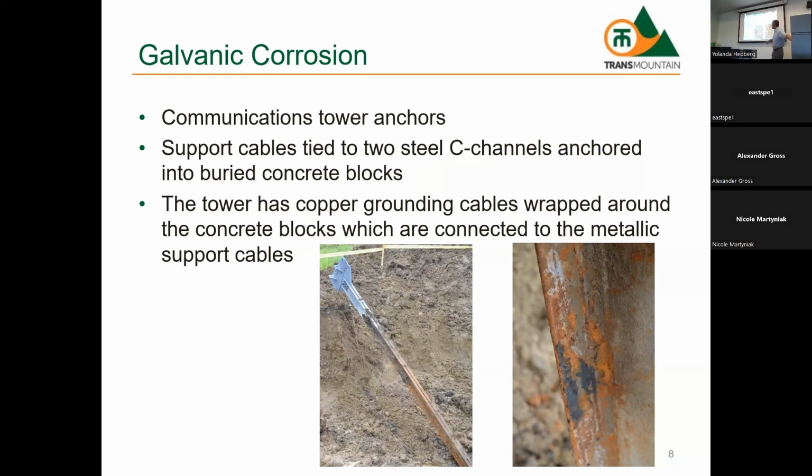Okay. So you can see that this portion of it was above ground. So the galvanized stuff that was in the atmosphere wasn't corroding. What was buried in the soil was corroding. But the galvanized steel above soil did also not protect the other steel inside the soil. Oh, I see. Because it was not immersed.